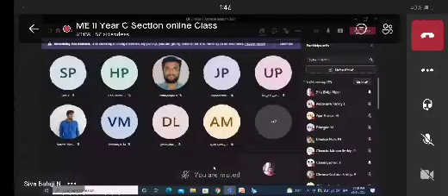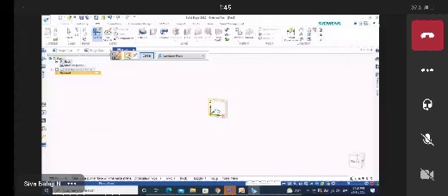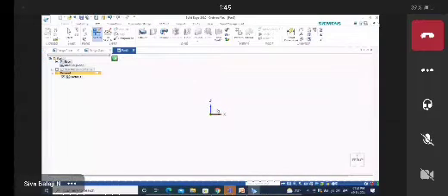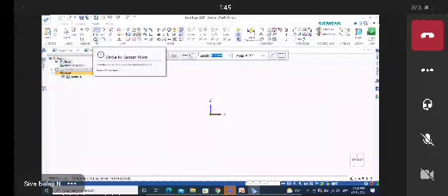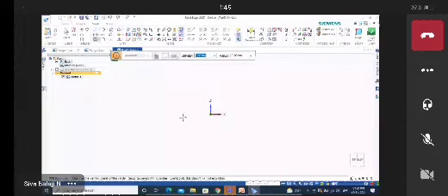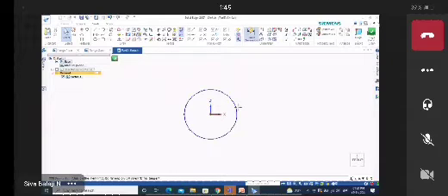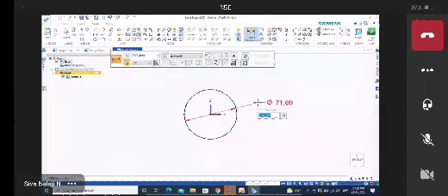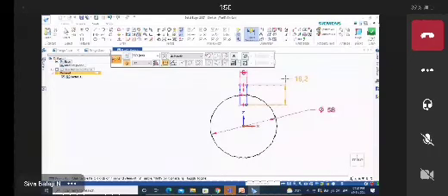You can select that plane, select the circle command, and draw a circle here. Give the dimension for this circle, 8 is given. Now you can check it here. Now select the rectangular key slot, select any point here, and give the dimension for this. How much? 6 mm. Okay. Now you can check it here. There are unwanted entities on the top side.